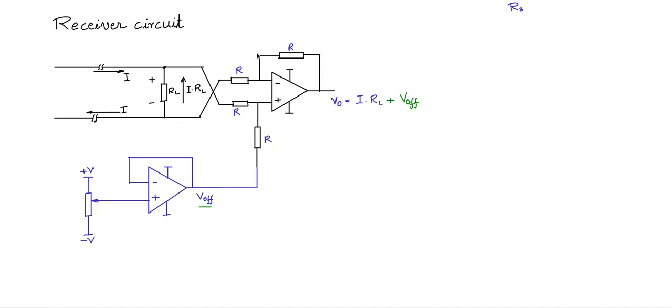Whatever this V0 will be, whatever this voltage plus this offset component which will come here. So the offset component, if I divide it by 2, because it's a superposition value, R divided by R plus R, and into 1 plus R by R, which is into 2, so which will come as an offset component. Okay, so this is the concept so that I can manipulate offset, and I can also manipulate the gain of this to get the zero and span adjust.